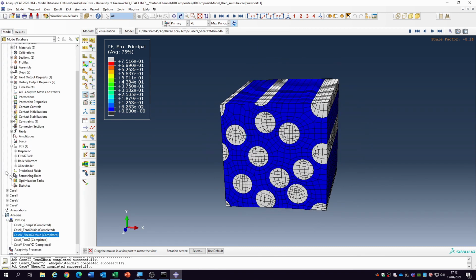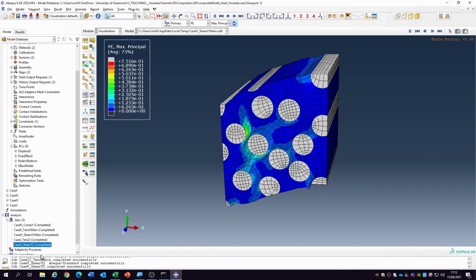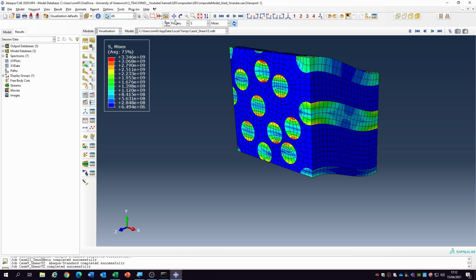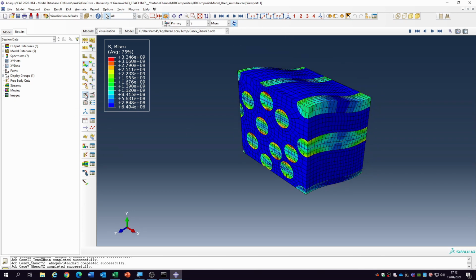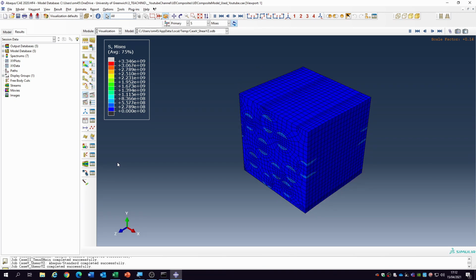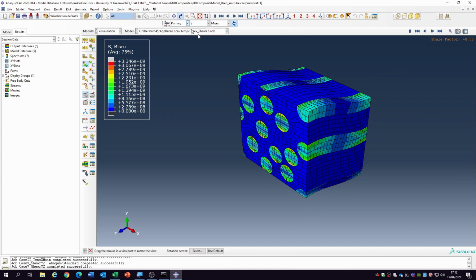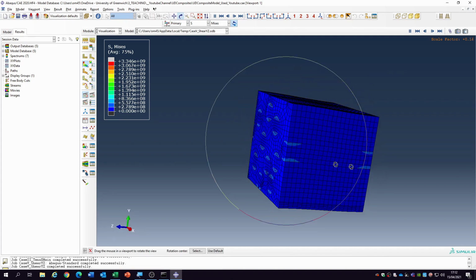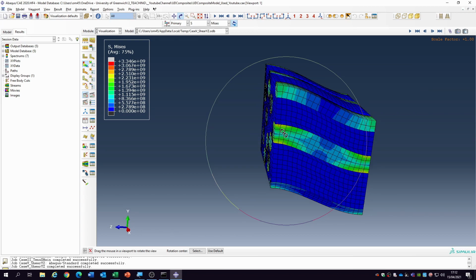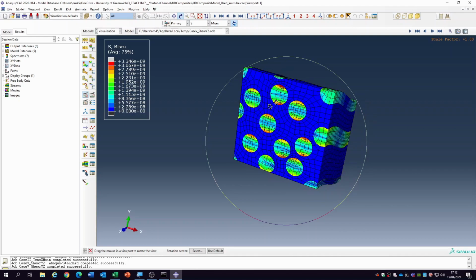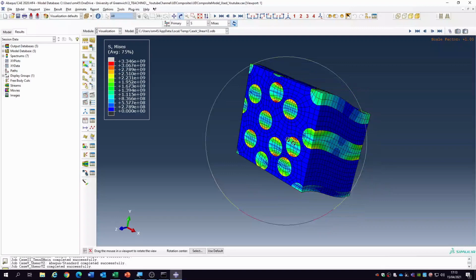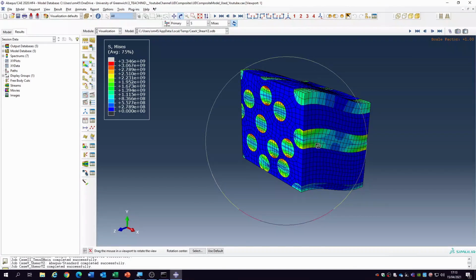And then the final case would be where you look at the shear in the fiber direction. So basically we're shearing in the fiber direction and it shows some really interesting results. If you animate that, obviously the fiber is being pulled, the back is fixed and you're shearing about this fiber direction. Obviously the fiber properties will dominate the behavior of the system significantly, and you can see a kinking profile in how the fiber looks, and differential values on the fiber on those faces. So some interesting results that you get by studying what's happening in the fiber direction.